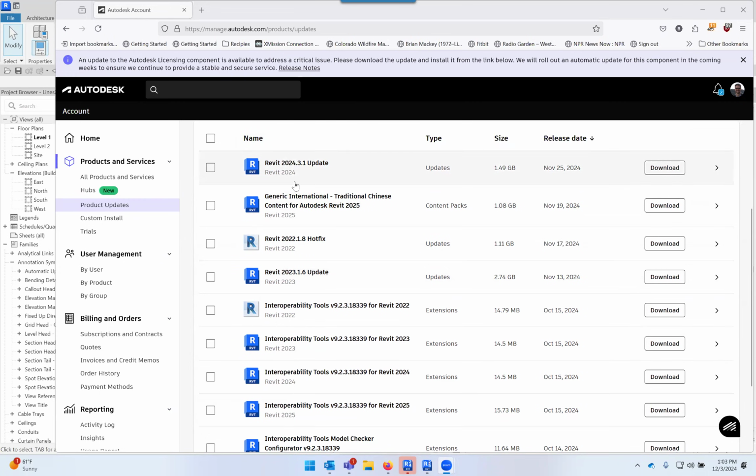So if you guys are having a lot of those schema issues, that's what the point one update is for. I know the majority of those deal with Unify or content catalog, but I have had other issues with those schema issues. So theoretically, 24.3.1 did fix that. There was a really convoluted process where it says if you install this and it still doesn't fix the schema issues, you have to unload all the links, reopen all the files with the links unloaded, save them all, then reload all the links, and that'll fix the schema issue. So I thought that was pretty bizarre.